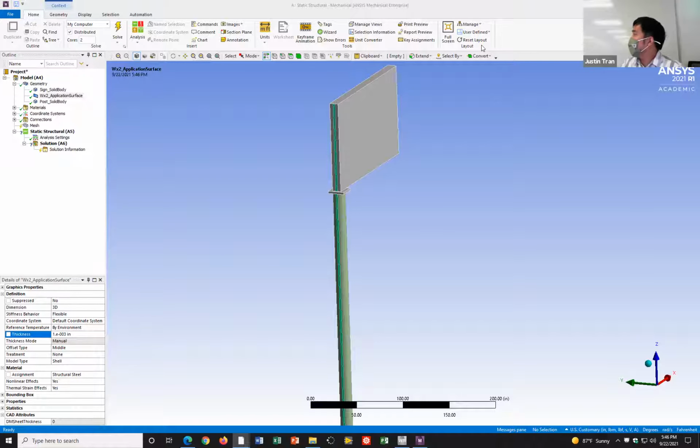All right, any questions on this so far? Okay. Oh yeah. I can't find the thickness. Yeah. So all the geometries, the three of them, all have question marks. Oh, they're all question marks. Let me check real quick. Oh, that's because you need to assign the materials. Yeah.